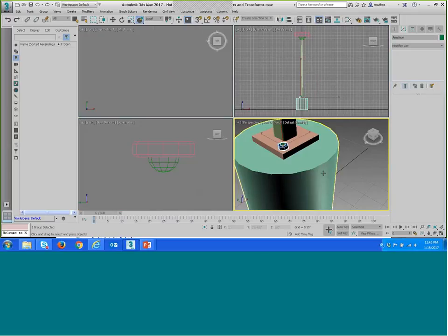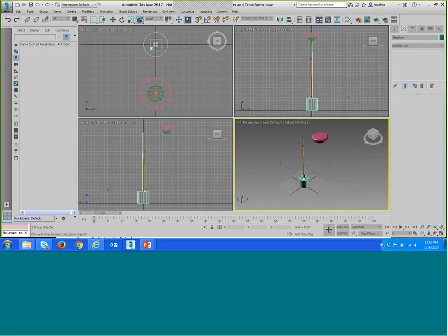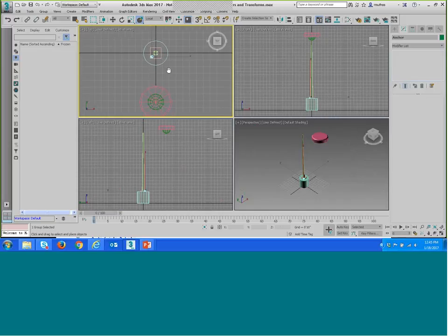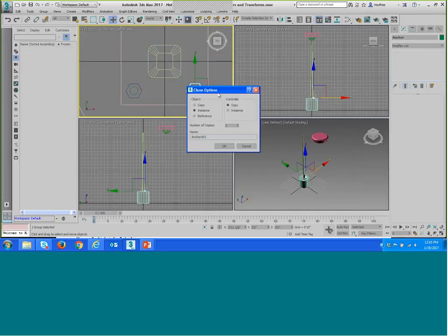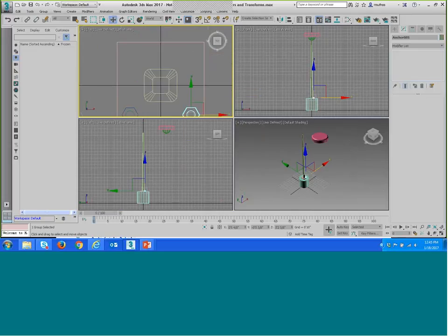So if we go back into, I'll say, zoom select all, go into here, so that's where we placed it. We can just move it now. So we use the move command, using the shift option, copy it and move it onto the other 4 locations. So, okay, and then okay.